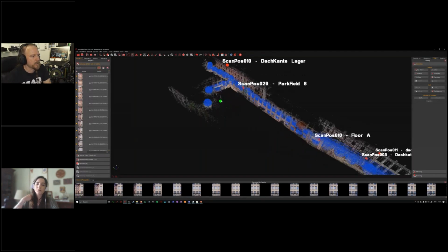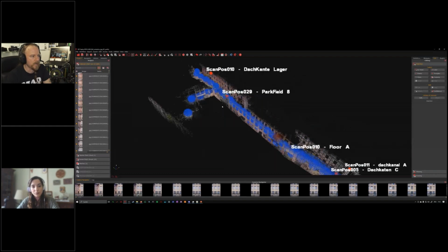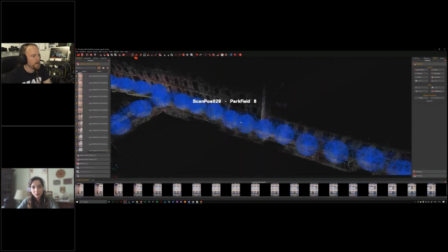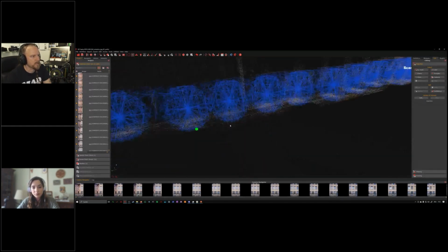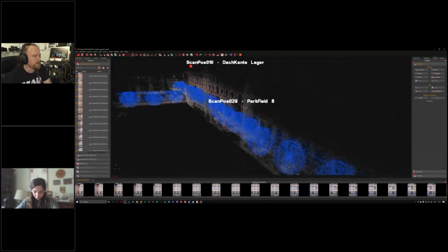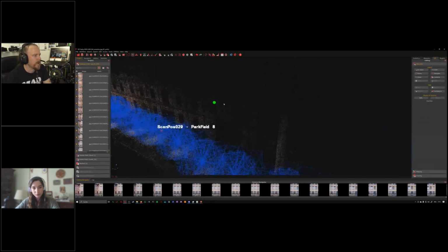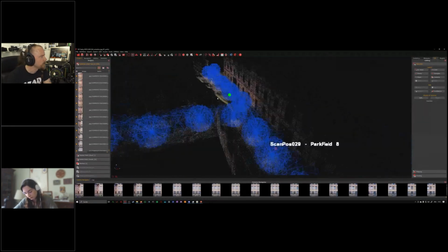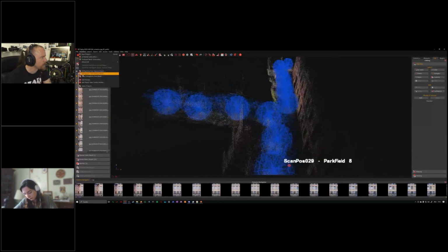So what photogrammetry actually does, in the process called structure from motion, is putting each pixel over several pictures into the 3D space and projecting that. The result will be, at the first stage, like here, that's actually in Winterthur, close to an old industry area. Putting it in the sparse cloud state as the first state, an actual representation and alignment of each or a few pixels into 3D space. So you end up having here, maybe I should make the points a little bit bigger because